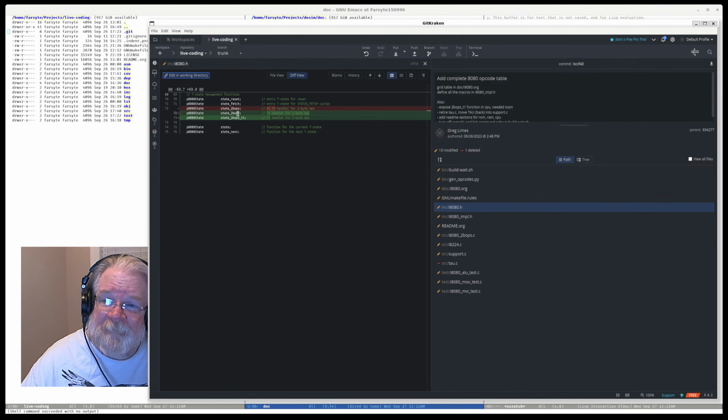I realized that we had a 2-byte operations handler. This is for handling the second byte of a multi-byte instruction. And we provided a handler that goes in the last T state of the existing machine cycle. But I can see by looking at the diagrams that we're going to need a way to say, run this as the next T1. So I'm exposing this state 2 bops as part of my 8080.h.